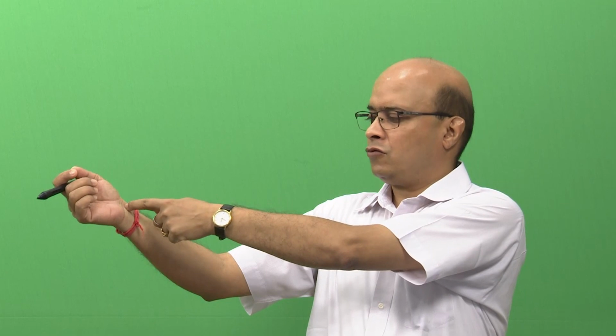If you look at our hand, for example, the position and orientation of the end effector, that is my hand here, is related to the joint variables. There are two thetas here, 2 thetas here and 3 thetas here. So, inverse kinematics basically gives us the relationship between the end effector position and orientation with respect to the thetas.